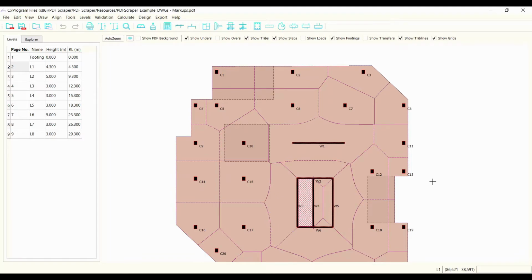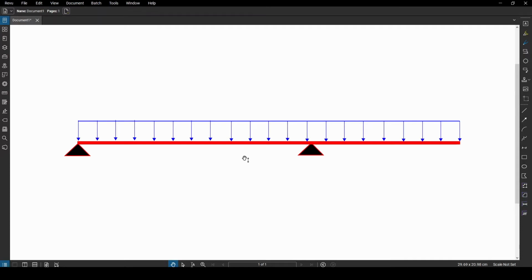The next thing for us to consider is something called a shear throw. I'll just flick over to a diagram briefly and explain shear throws. So take this classic example of a linear propped cantilever type arrangement with a UDL load on it. If we were to think about the one-dimensional tributary width of the right support, then we would take the length of the cantilever plus half the length of the backspan.